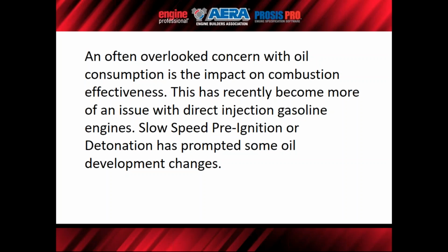Those engines are starting at about 16-to-1 compression ratio, and now we're running gasoline engines approaching 13-to-1 compression ratio, whether that be static or dynamic from the artificial aspiration, but we're getting some pretty high cylinder pressures in gas engines. So that's also something to consider. We'll probably have to be more cautious of our choices on stem seals and their impact on oil consumption.